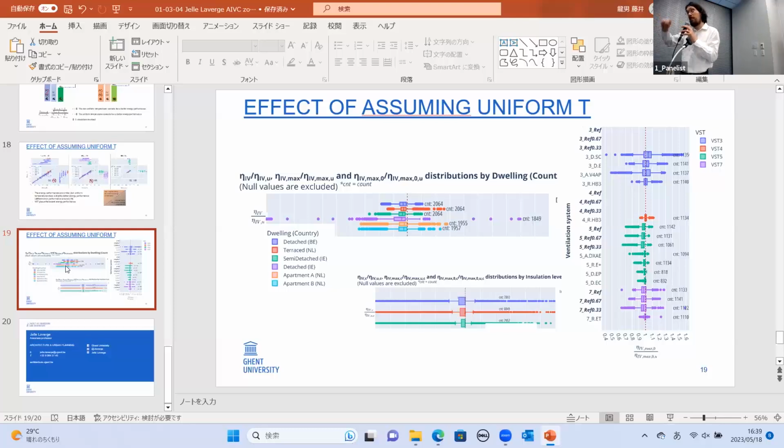So the worse the heat recovery efficiency of the unit is, again, the bigger the ventilation losses in the total heat loss. And so there we see a somewhat bigger effect. That's the purple ones. And you see that those are a little more shifted than the other ones. Thank you. But to give you an idea, even then, the average effect is on the order of a few percent, like 4 or 5%.